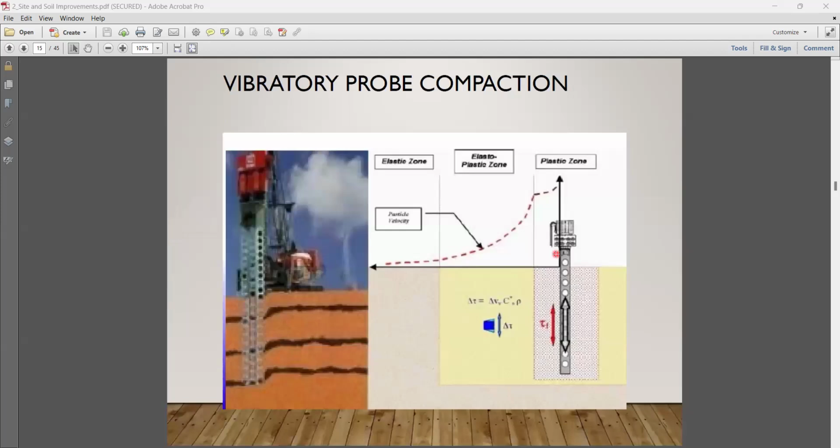So this is the vibrocompaction. You can see once the probe is inserted and vibrated, on the left side it's not settled, and on the right side you can see it as it is. But when we vibrate, it will come down. It means voids will get removed.